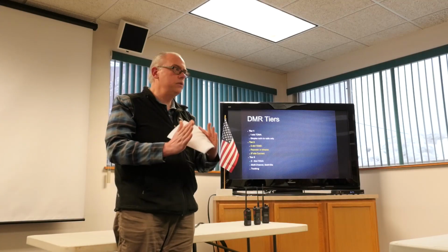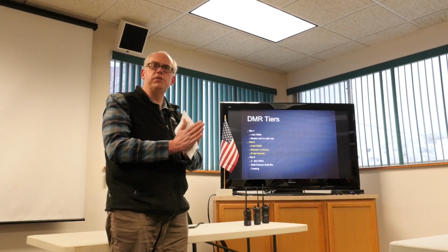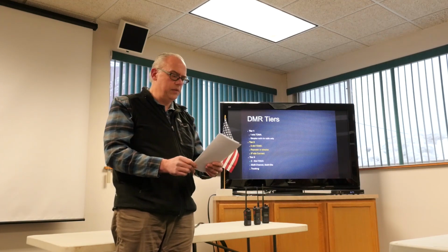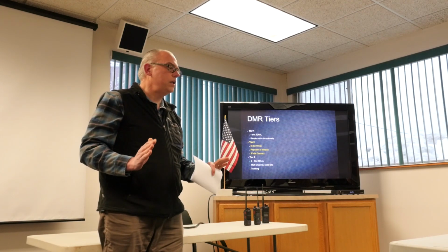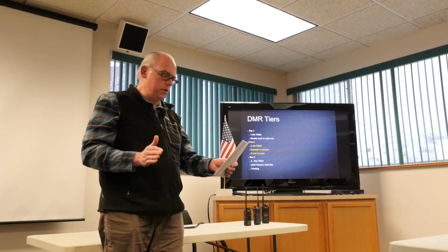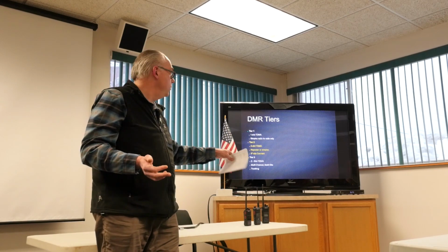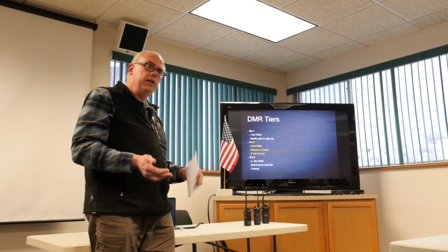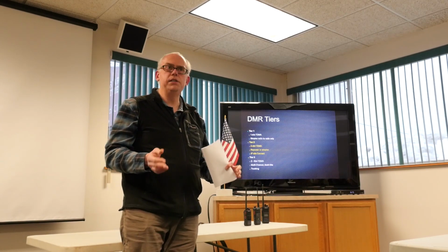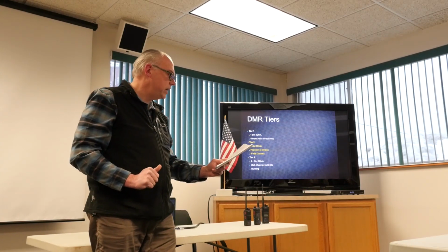Like I said, you can have two simultaneous conversations going on that DMR stream at the same time, but Tier 1 radios can only do one conversation at a time, and that's going to be important to differentiate when we move into those other tiers. So you're really going to find a Tier 1 radio is only suitable for simplex, because it can only use one of those time slots at a time.